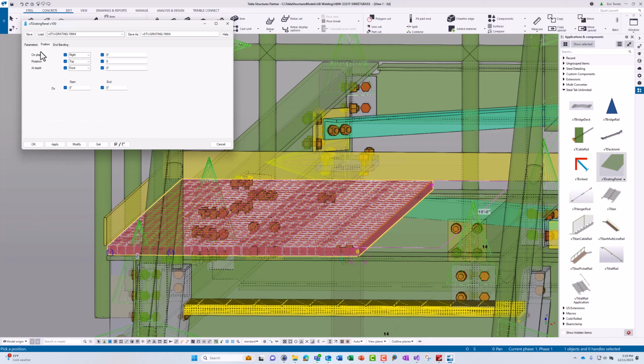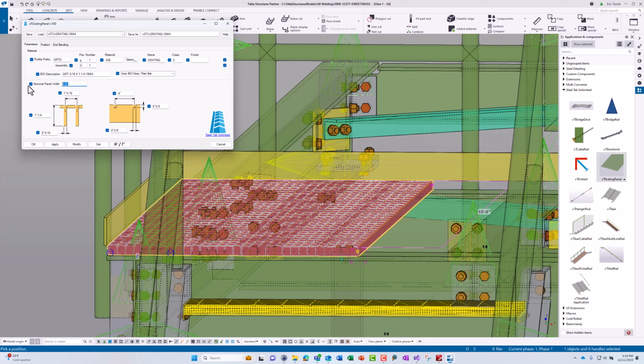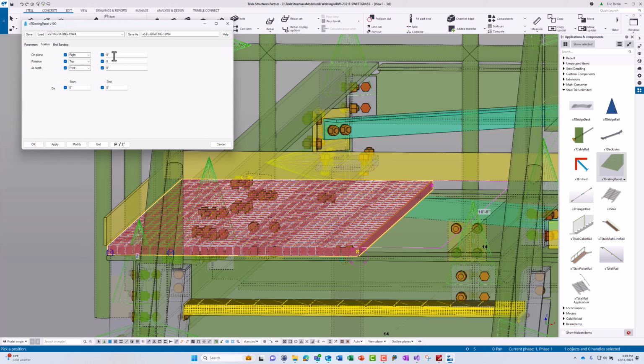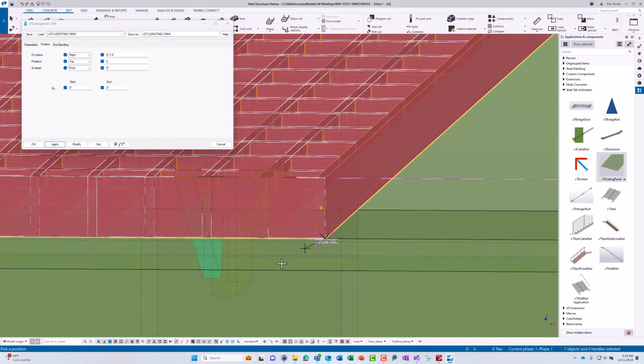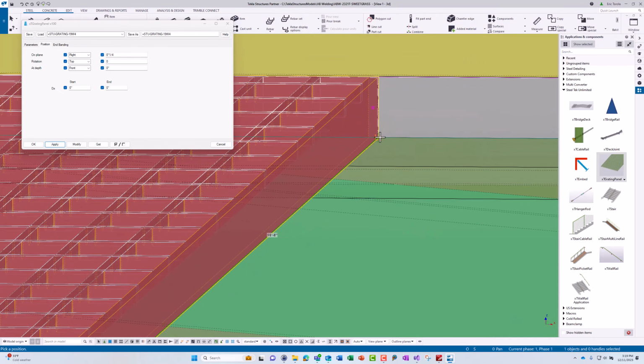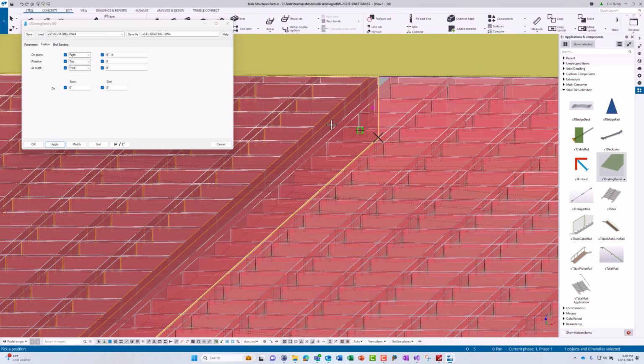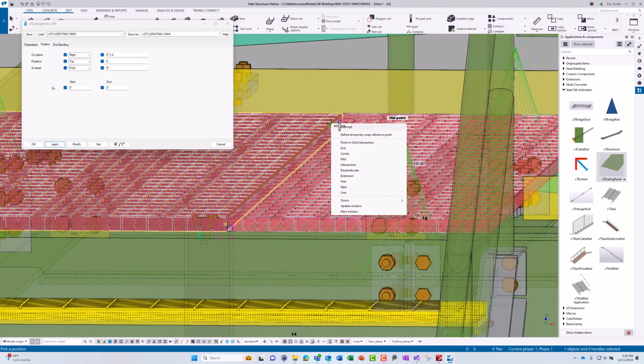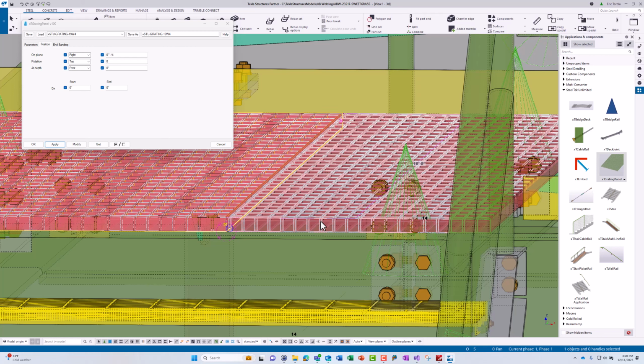To continue this demonstration, we're going to change the panel width to a nominal width of 24 inches and we'll set the on-plane offset to a 1/4 inch to get a space between our two panels. As you can see, we're creating these panels. As we're creating these panels, the xTGratingPanel plugin calculates the actual width based on the bearing bar thickness and the spacing of the bearing bars.